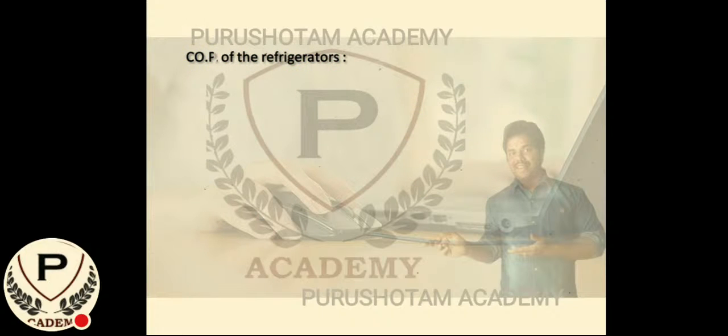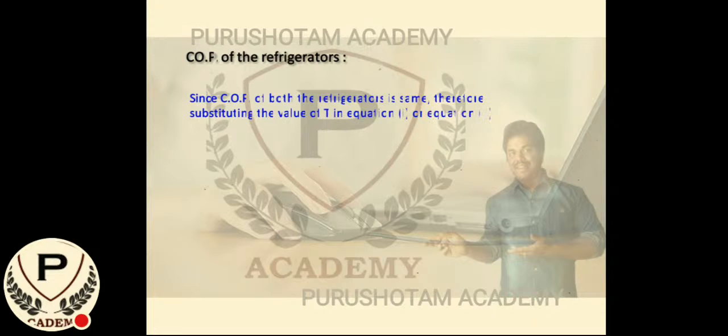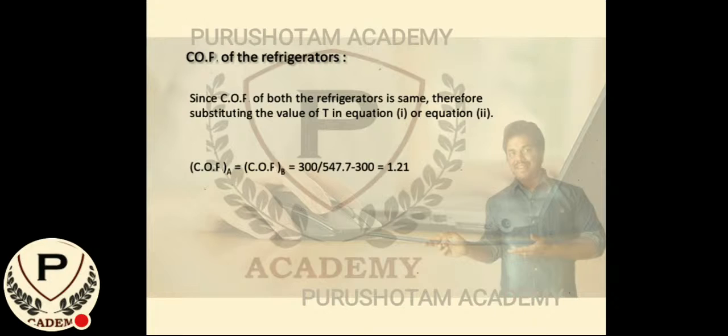So we have to find out the COP of the refrigerators capital A and capital B. As we already know the values of COP which are represented in equations 1 and 2. Okay, so since COP of both the refrigerators is same, therefore substituting the value of capital T in equation 1 or equation 2, we will get the COP. Okay, so COP of A equal to COP of B, that equal to 300 divided by 547.7 minus 300, that equal to 1.21. Therefore COP equal to 1.21.